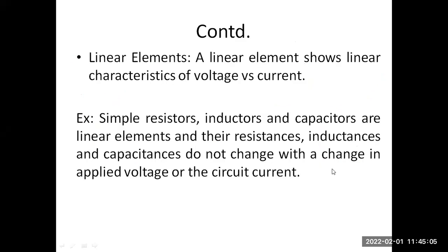So what is the definition of linear elements? A linear element shows a linear characteristic of voltage versus current, as I have just shown you. Examples of these elements are simple resistors, inductors, and capacitors. Their resistances, inductances, and capacitances do not change with a change in the applied voltage on the circuit element.